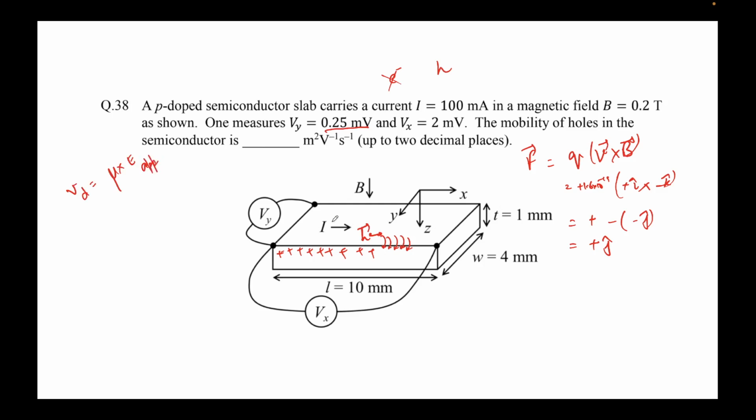So you see, the hole is drifting from here to here, correct? You can see it's drifting like this. Current is here, the hole will also go in this direction. So what is the electric field applied? The electric field applied will be nothing but V applied divided by length. Length is L. This we need to know. This we calculated from the formula of current that we had.